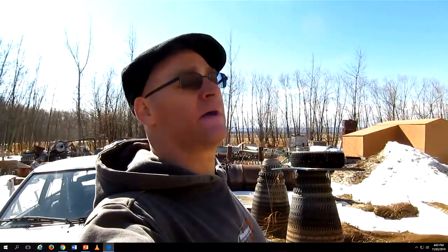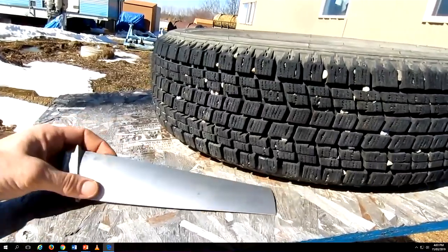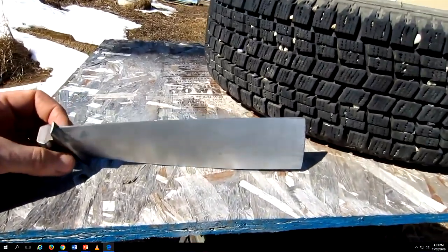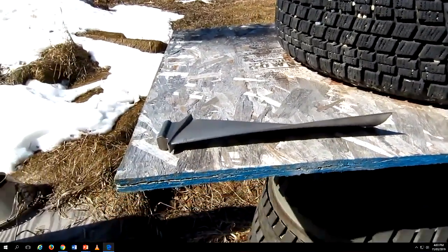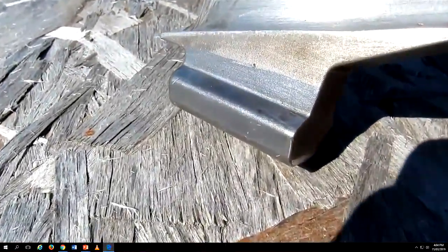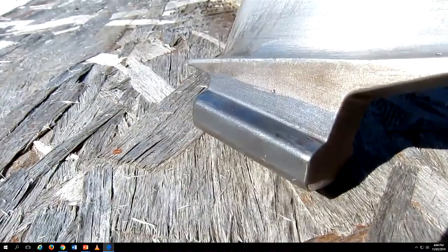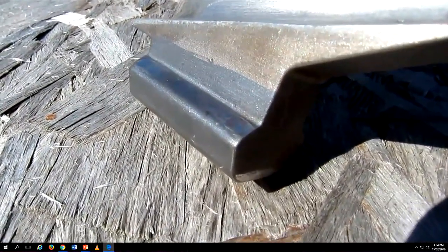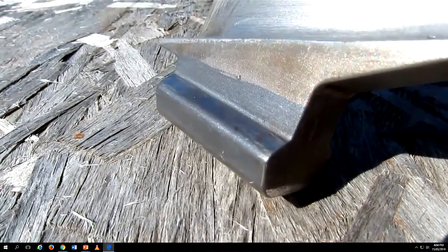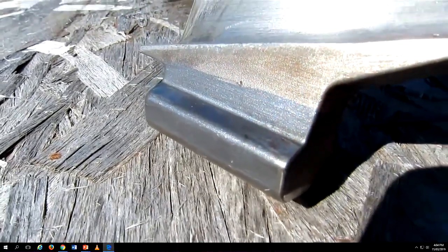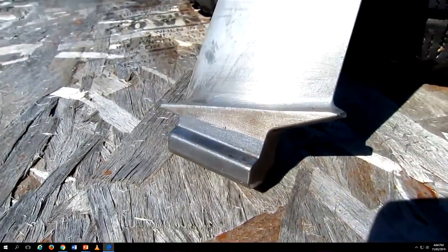Okay, we're out here in the graveyard of turbine engines with a turbine-powered helicopter in the distance to look at how a compressor blade wears out. There's two examples on this one right here. This is a stage 1 blade from an LM1500, and let's see if we can get in there real close. Okay, we're moving in here to the blade root, right along there. This is the surface that bears the centrifugal load of the spinning compressor rotor, and I hope you can see there's some wear. This blade, on inspection from removal of an engine, was decided there's too much wear there, so we junked it.